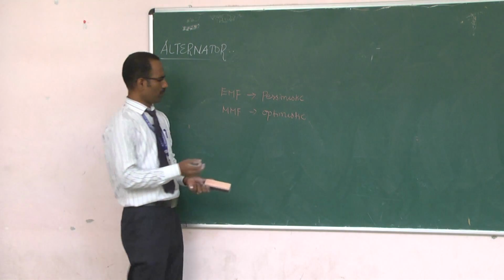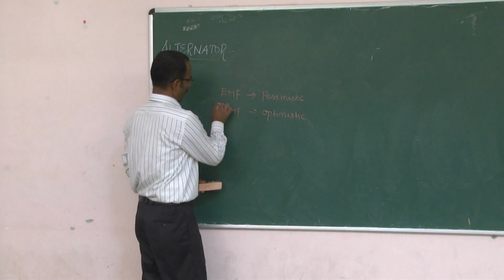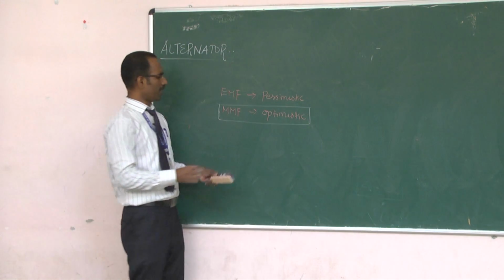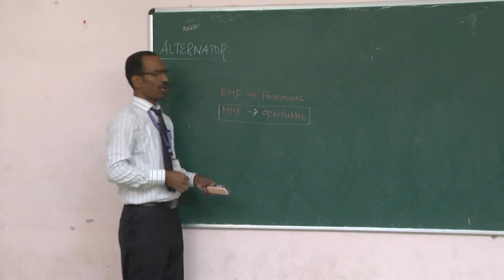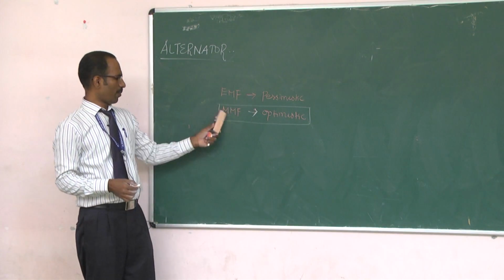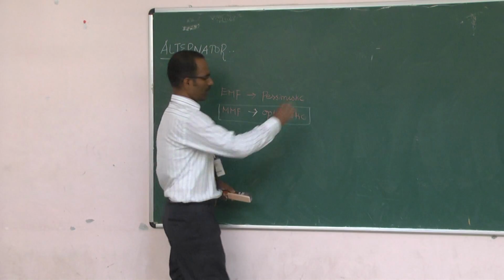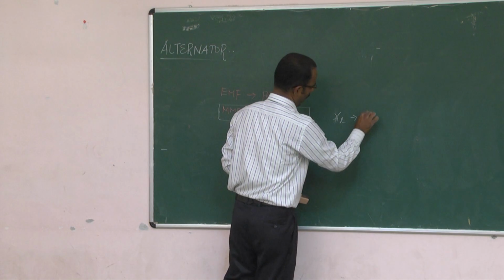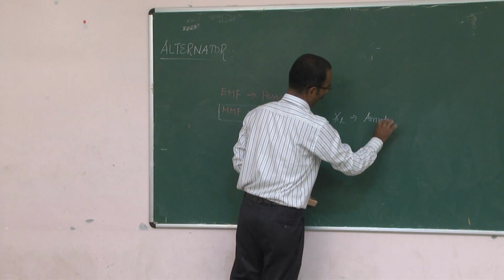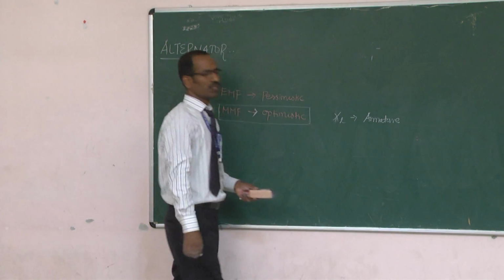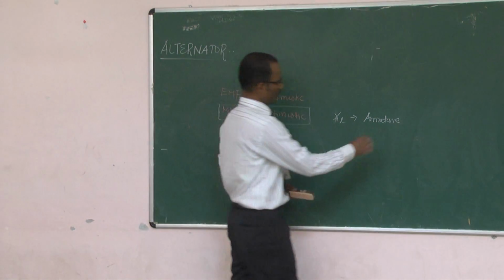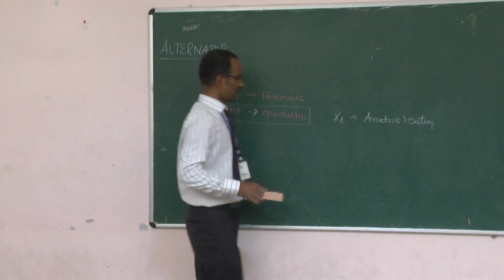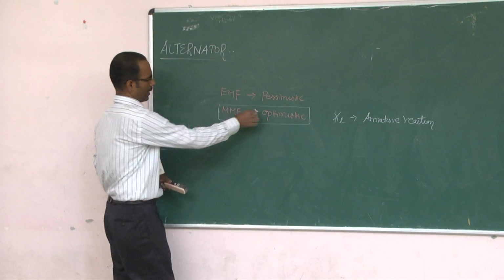The E0 value found from this is always less than the actual, so we get a reduced regulation here. The technical reason is that in the MMF method, we consider the leakage reactance also as armature reaction effect. The leakage reactance is also added with the armature reaction effect, so we get an answer less than the actual value.